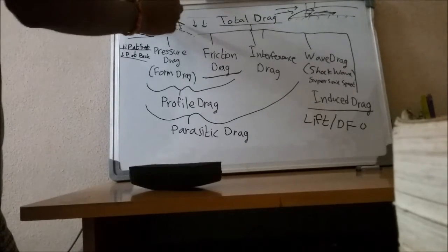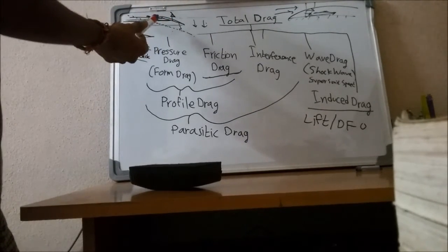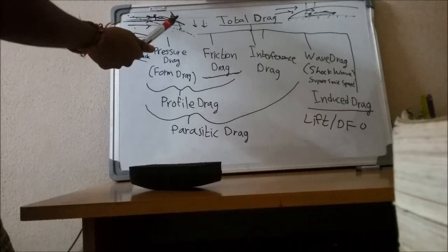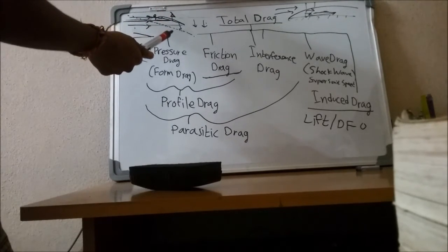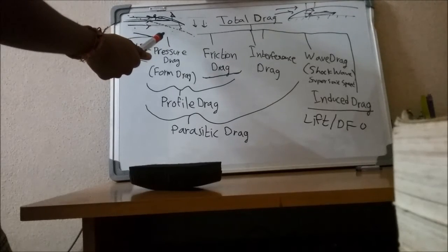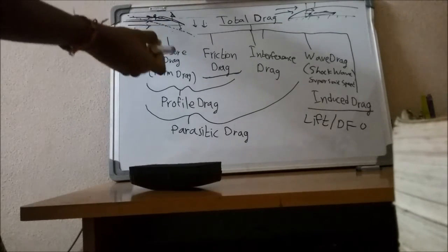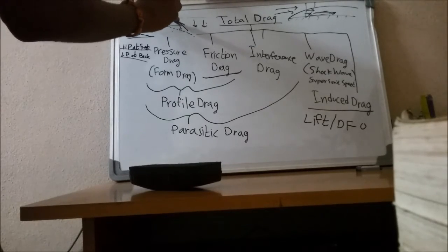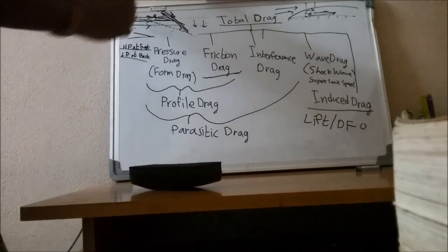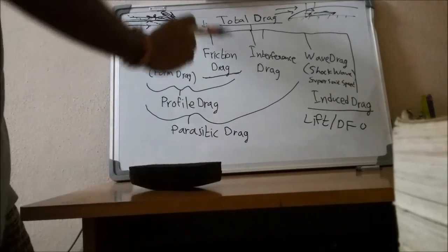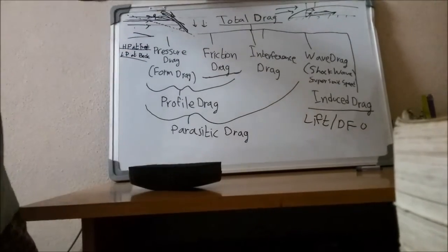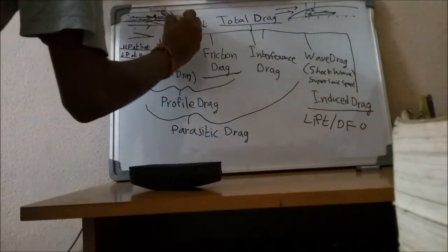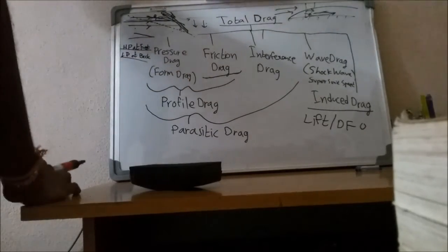As we have discussed earlier, the effective angle of this wing has reduced from 25 degrees to 10 degrees, say in this particular example, then you will have to again raise the angle of attack to 25 degrees. So in reality the wing could have been even more inclined. If you put the wing at such high angles, the drag force is also going to increase.